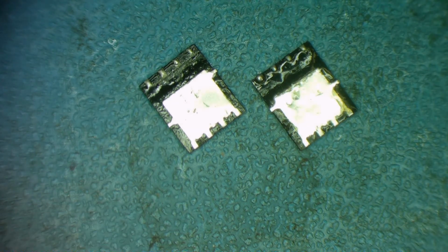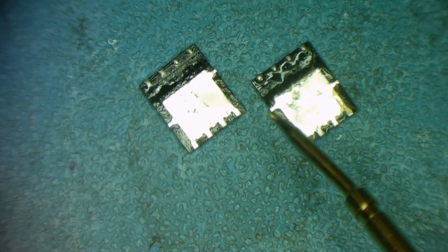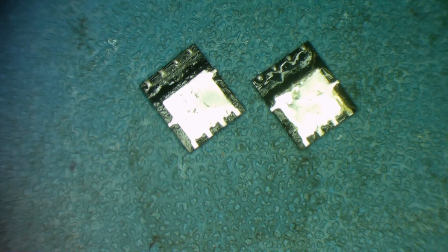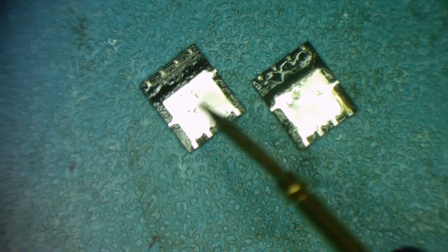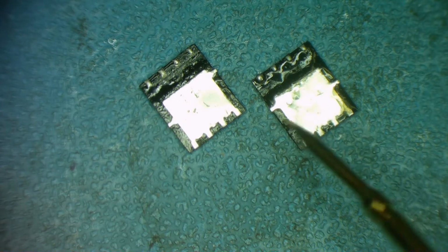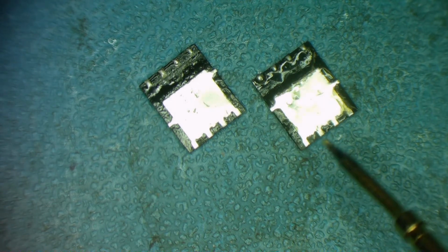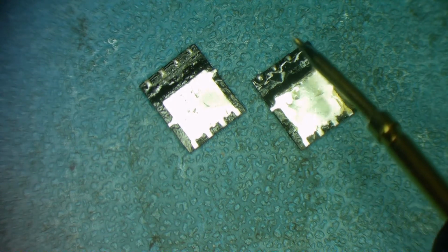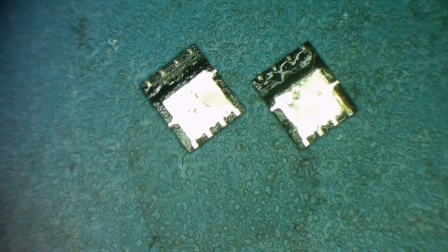It's funny because all these seem to be connected together, but you said one of them is the gate, which is interesting. But let's see what we can actually do, see if we can test this. It actually has a different layout than the one we just looked at. Maybe that's the wrong datasheet for these. But I'm pretty sure 3 of these will be drain or source. The other one will be the gate. Let's see if we can prove that.